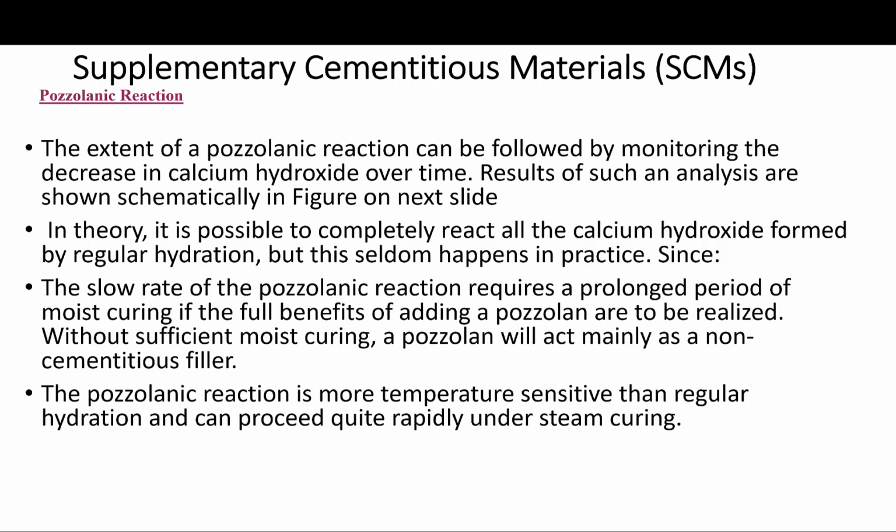In fact, it is important to realize that the slow rate of pozzolanic reaction requires a prolonged period of moist curing if the full benefits of adding a pozzolan are to be realized. Okay, so without sufficient moist curing, the pozzolan will mainly act as a non-cementitious filler.